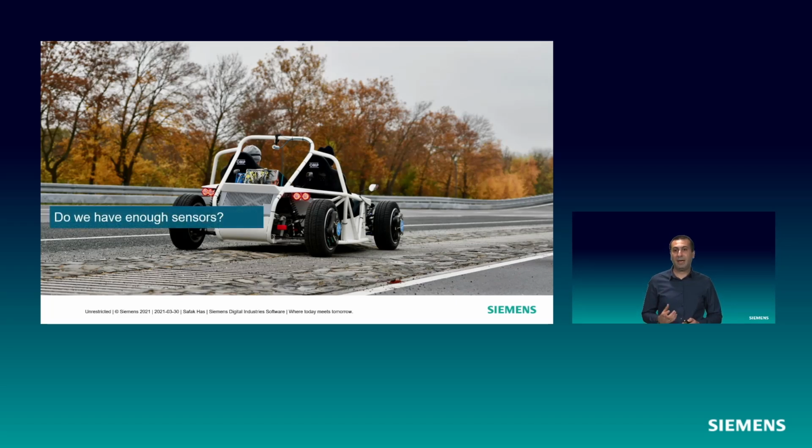So first of all, do we have enough sensors? This is really taking us to think about the resources that we actually have. Another important challenge will be, even if we have enough sensors, do we have enough time and manpower for the instrumentation? Because again, for durability, we are mostly taking into account long measurements, long durations, let's say. Which will cause us a lot of effort, a lot of manpower during the instrumentation. Because, as I mentioned, we put a lot of sensors on a car when we consider durability testing, which means that the instrumentation will also take quite some effort, let's say.